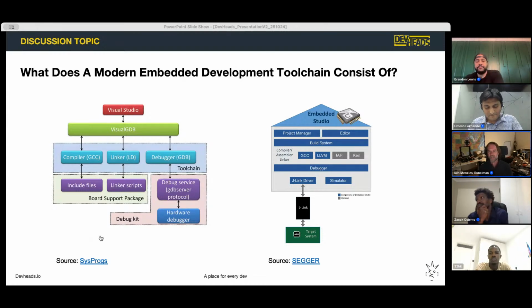There are choices on every aspect of things, but it will always be some kind of variation of GCC, GDB, etc. But given that most of my work is based around Yocto, when you create your Yocto project, you have an option of creating not only the toolchain, it's a complete software development kit that contains a toolchain. When you build your image, you just go for the option of give me the complete SDK, so I get a full toolchain from my build. So because I stick in Yocto,